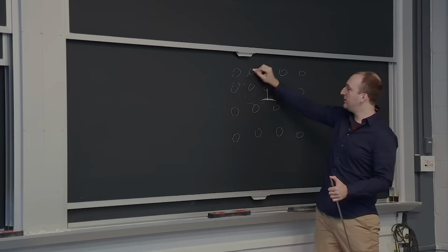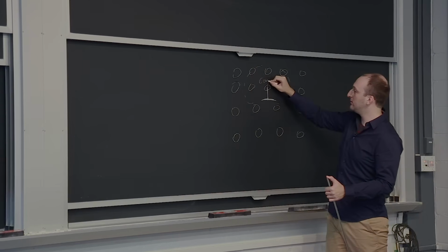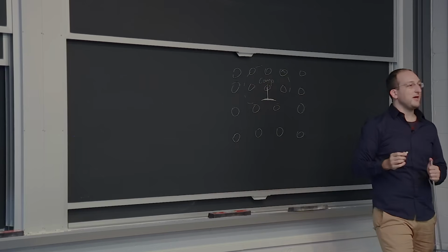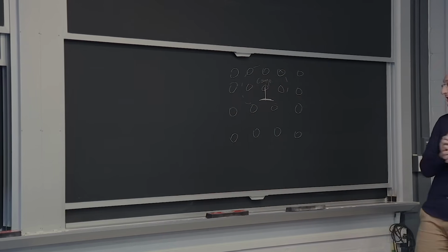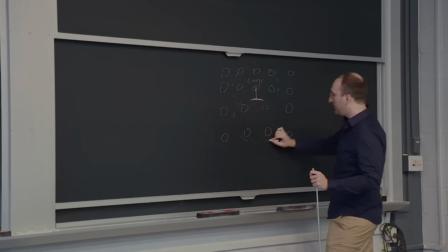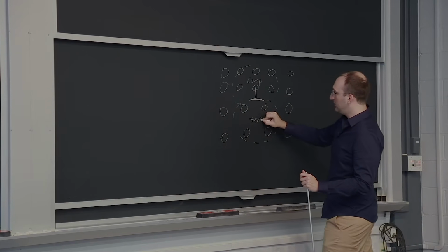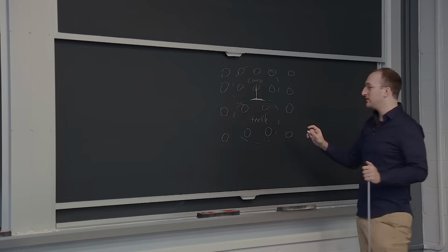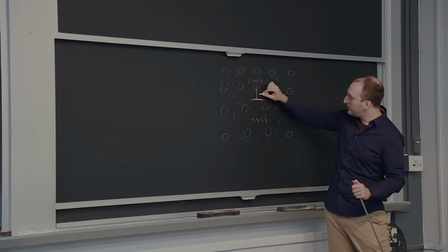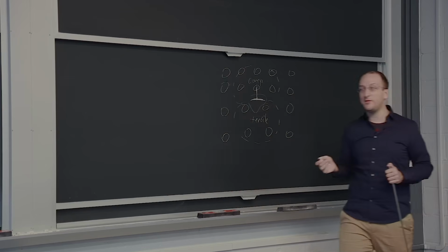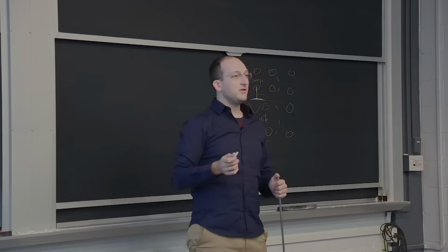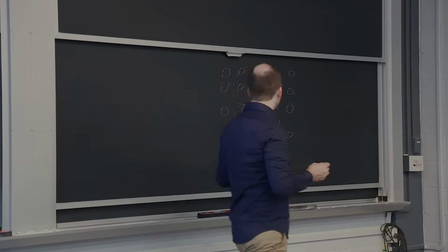This region of space right here is compressively stressed. There's more atoms in that space than there want to be, and so it's kind of crammed in there. While this region right here is in what's called tensile stress. There's almost some space like right here where there's too few atoms and they kind of want there to be more. And these dislocations can feel neighboring stress fields.